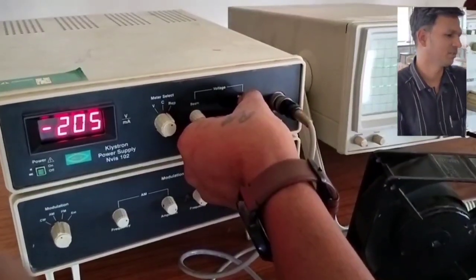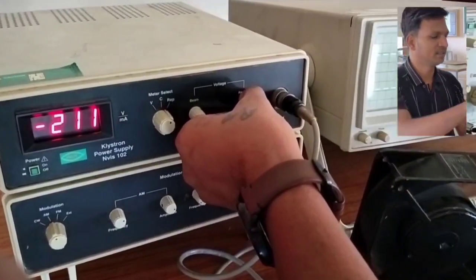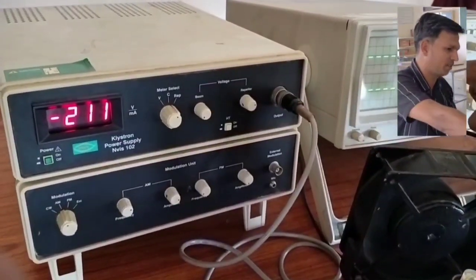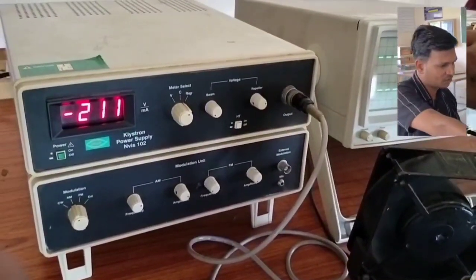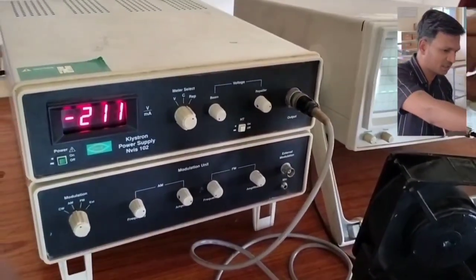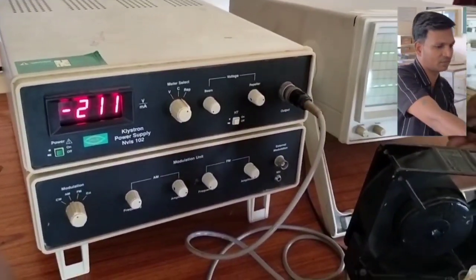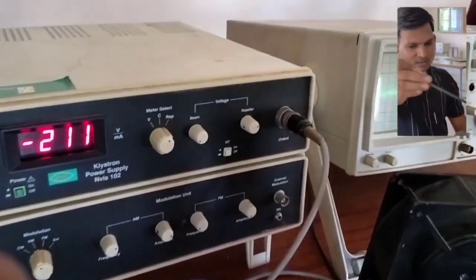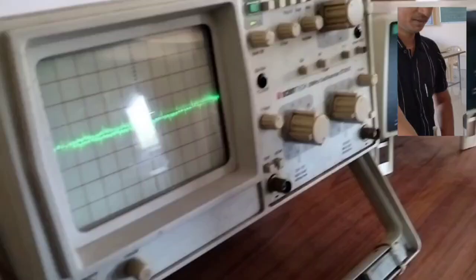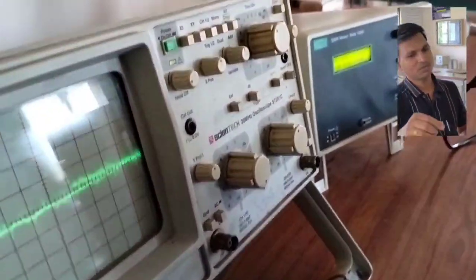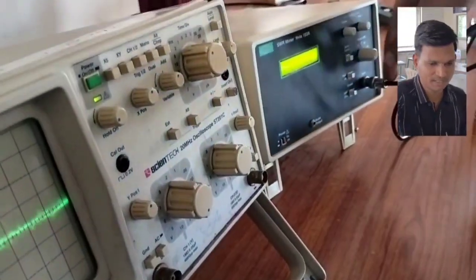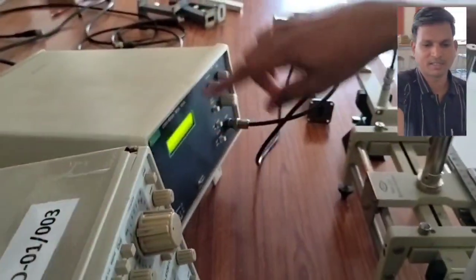For calculating the power, students, the amplitude should be in the maximum position on the CRO. So we need to keep it in the maximum position. After setting the maximum position, you have to remove the probe from the CRO device. There is no need to change anything in the SWR meter. I removed the probe from the CRO device, and now I simply connected it to the SWR meter.